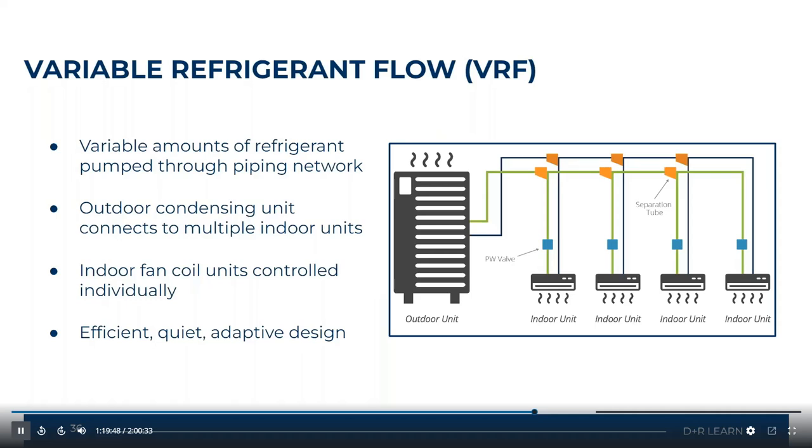The VRF systems do not require a lot of refrigerant to be piped through an entire site or zone or facility. But the really cool benefit about these systems is that they can save a lot of space where you would otherwise have to dedicate that space to ductwork for any type of traditional hydronic system.